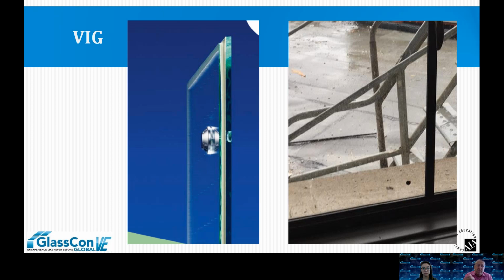But on most projects that are larger size lights or large fixed windows, you don't really see it. And even still, if you actually look at what it looks like, your eye kind of looks through some of these darker colors. And really, with the mullions and muntin bars and different things like that, there's a lot of other things that are distractions. So it's something to talk about, but practically speaking, it's not a massive impact on the vision area and what you see. It actually looks kind of like a regular IGU in terms of reflection and transmission and all those other sort of things. Really, it's going to look the same as a regular IGU.